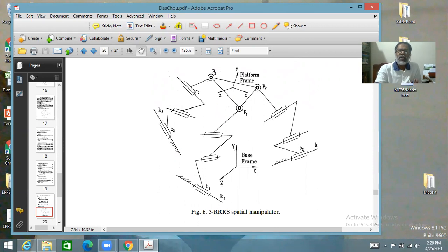So the moment equation of only this about this axis, the moment equation of these two together about this axis, and the moment equation of the entire 3-link assembly about this axis. And that is how we can construct the scalar equations which we need.